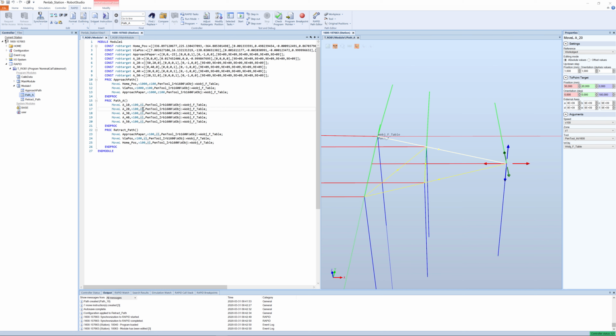If we change the Z1 to Z10, so we see what happens with the corner when you do this kind of interpolation. So before it approaches that position, it starts to bend over to the next one within a distance of approximately 10 millimeters. So it's pretty nice. It would also change the speed of operation.